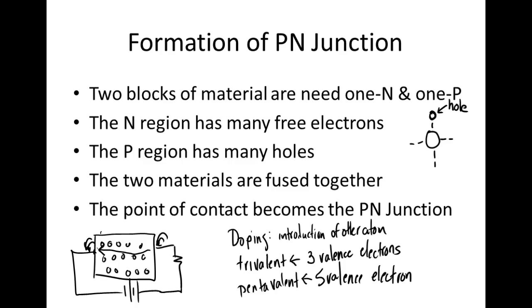So what we say in one that's been doped with trivalent, we refer to this as P material. Even though it doesn't have a P charge, it's called a P material, and we'll find out later on. And we call it the majority carriers. So the majority carriers in P material are what we call holes. Everybody follow this? Pretty interesting, right? So inside the P material, 99.99% of the current flow is holes. The electrons are not really doing it. Y'all understand? Which is pretty neat.